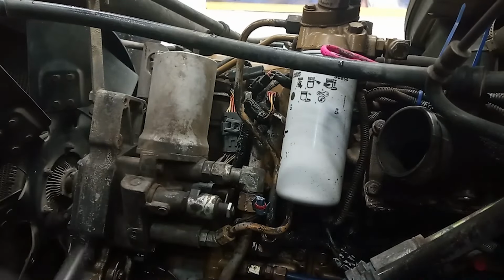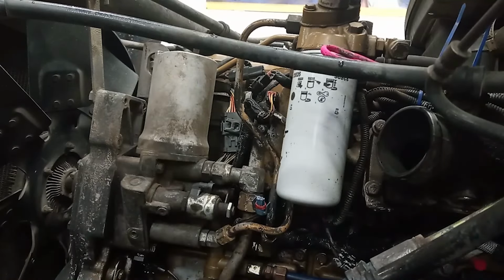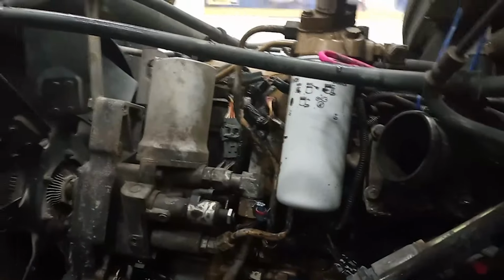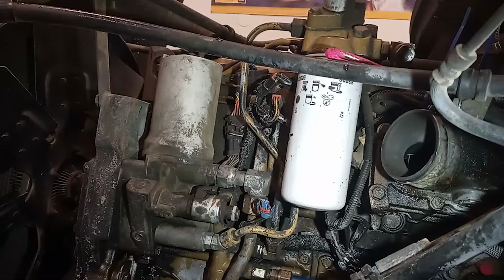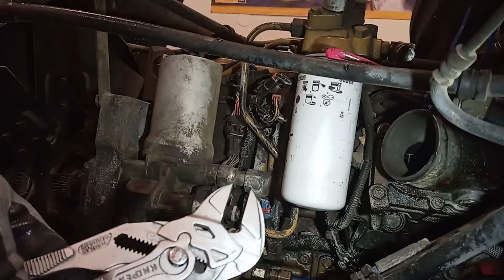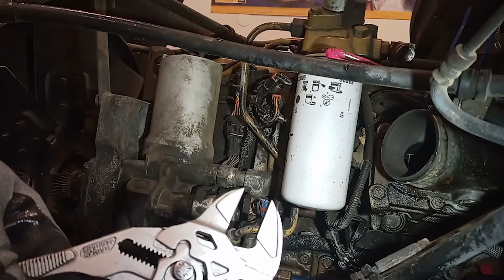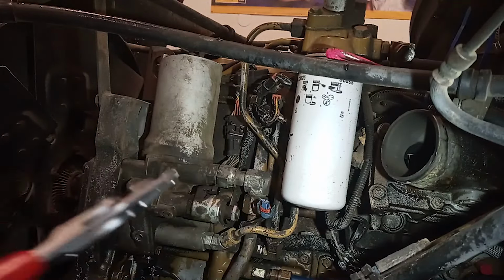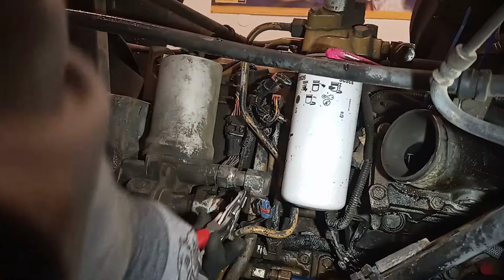It's also mechanical, so we need to test that, and we're going to use that little block-off solenoid that Cat makes, to basically bypass the solenoid and test the system without the control solenoid in place. Now, what I'm going to be using is something I've really grown to like, and it's not a crescent wrench. It's what I'd consider the next step in crescent wrench technology. It's called a pliers wrench. Knipex makes these, and I've got a set of three of them.